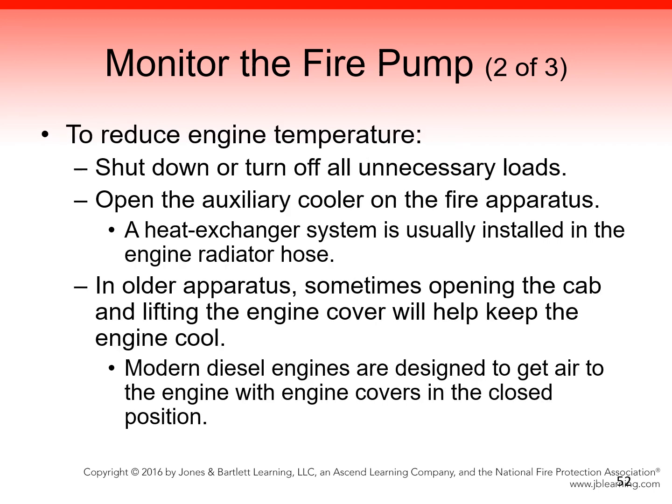First, shut down or turn off all unnecessary loads on the engine, such as the air conditioning system and external lighting. Next, if needed, open the auxiliary cooler on the fire apparatus. The auxiliary cooler is a heat exchanger system usually installed in the engine radiator hose. The heat exchanger allows the engine coolant to flow around the copper piping in the tube. The copper piping, which has cold pump water from the fire pump flowing through it, reduces the temperature of the engine coolant by conduction in the heat exchanger.